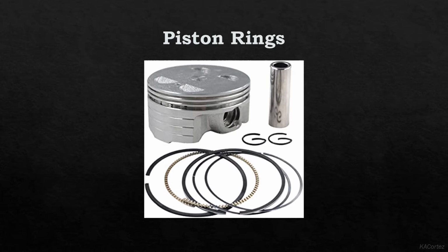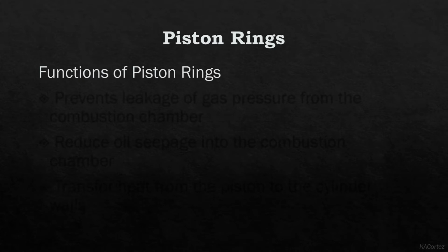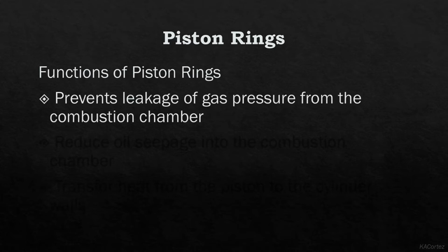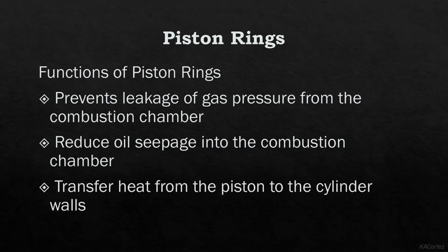Next is the piston rings. Here are several functions of the piston rings. First, it prevents leakage of gas pressure from the combustion chamber. Second, it reduces oil seepage into the combustion chamber. And third, it transfers heat from the piston to the cylinder walls.